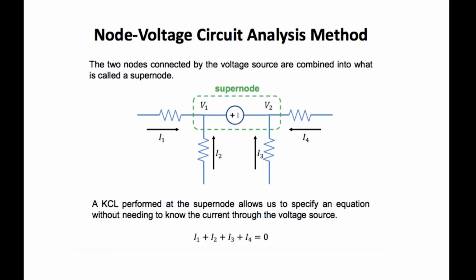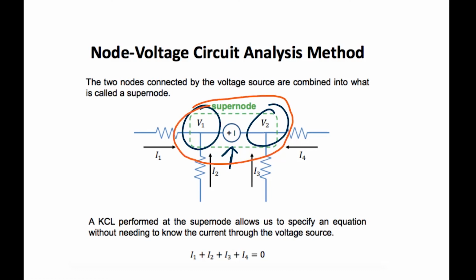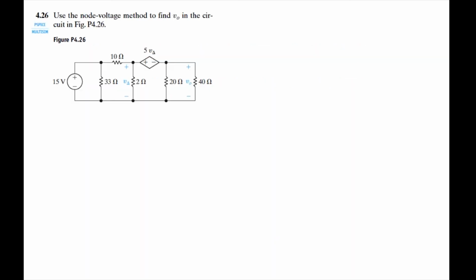Okay, the last thing is a supernode. What is a supernode? It's not Superman. It's 2 nodes sandwiched together with a voltage source in between them. That's all it is, and we call it a supernode because we can now treat it as one entire node. Let's call this node Vx. Alright, clearly you are masters of supernodes, and we're going to solve this question now.